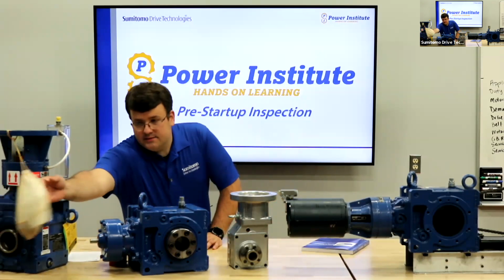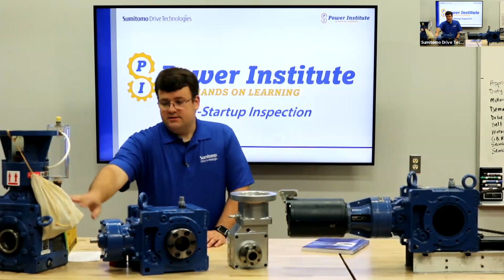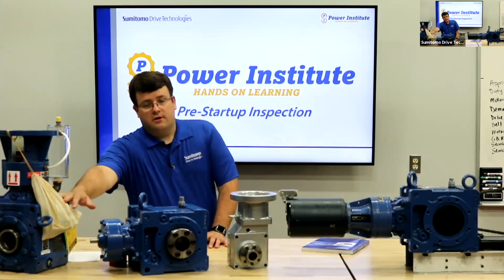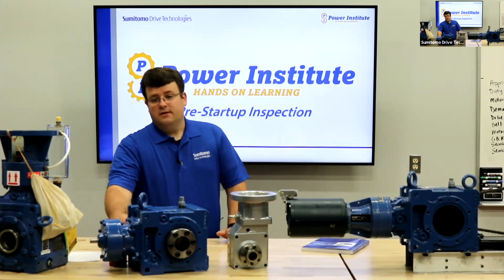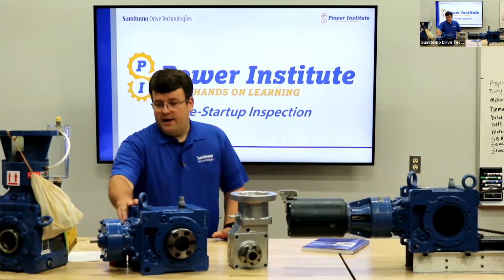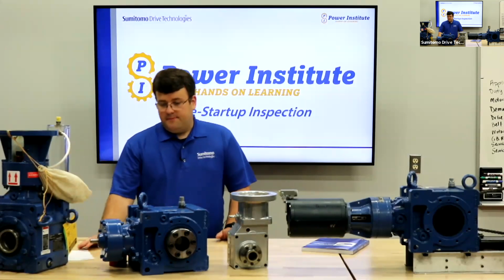Attached to every unit when they ship is the accessory bag. In there will be your breather, your coupling guards, and any torque arm hardware. Make sure that's all in there. Make sure it's all correct for the install that you plan on doing, as well as make sure that the torque arm that you ordered is included as well. Or if you didn't order a torque arm, make sure the one you designed will mount up to the different mounting provisions on the gearbox and make sure it'll mount to your piece of equipment correctly.